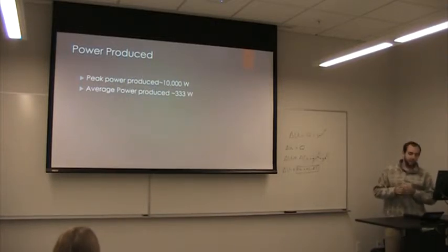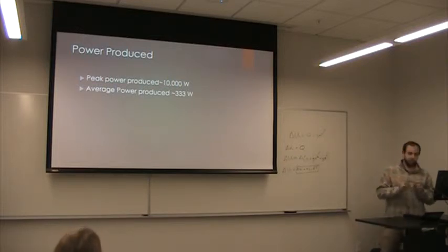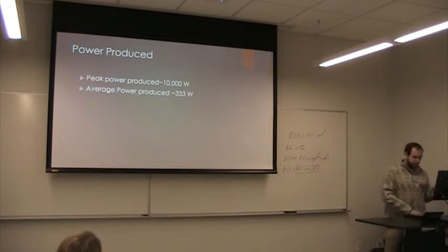You can't go too high because you run the risk of the generator exploding, which would be very bad. The system actually has a built-in safety procedure so that if the RPM goes above 8,000 and gets to 10,000, it shuts off, which is what happened to us. You have to adjust them inversely, so as the throttle goes up, the brake has to come down to get the power production ideal. I was adjusting it up and it hit that 10,000 RPM on the generator, which caused the system to shut down, which ended our data collection run.